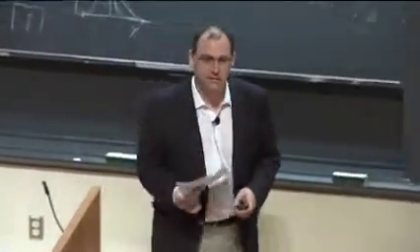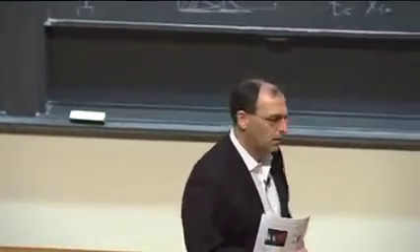I'll talk about statistical description of turbulence first. I will talk about some of the turbulence theory that might be helpful, and introduce the so-called K-epsilon model. Everyone has heard about this, without giving too many reasons why this model is used. Then we'll talk about a few combustion models, which we will not cover in any more detail, just very briefly, so that you have heard and know what the term means, really. And then, if we have the time, we'll talk a little bit about LES, or what's special in Large-eddy Simulation.